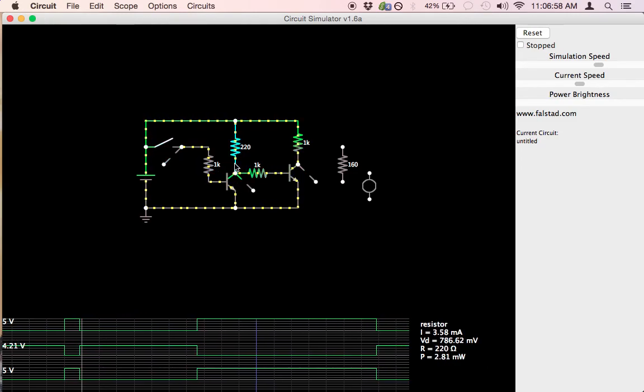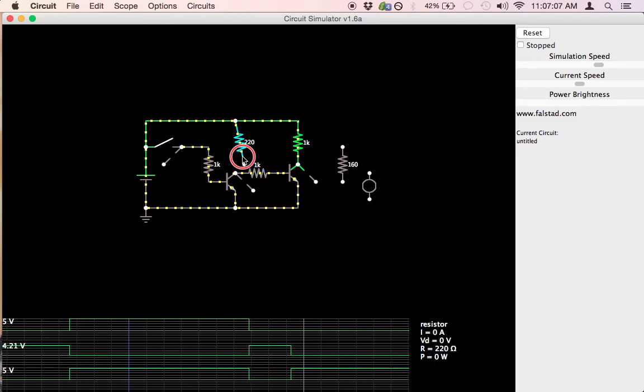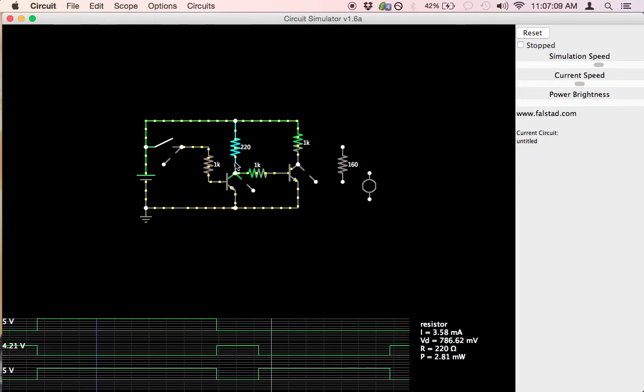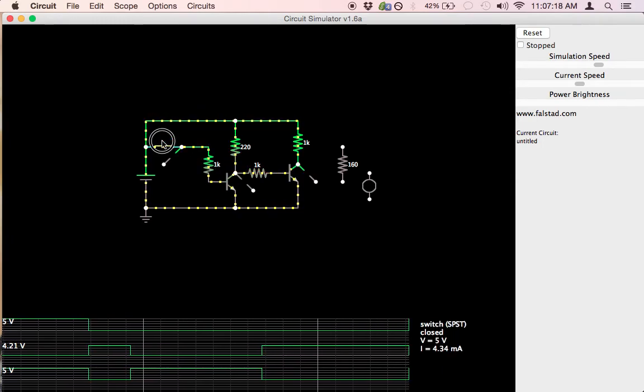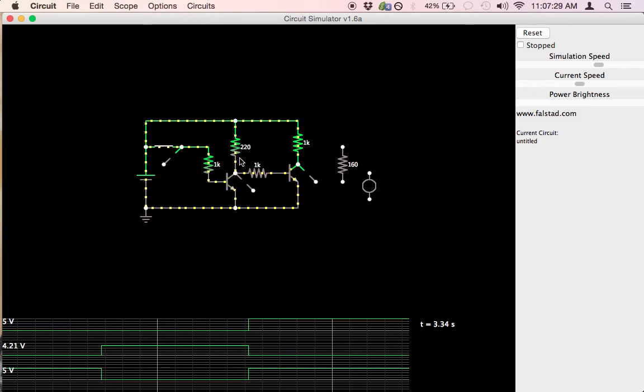By itself, the transistor does nothing. If there's nothing else connected to the collector, there's not going to be any positive voltage there because there's no place for it to come from. That's what these other resistors are for. These are called pull-up resistors, and they pull up the collector to the positive voltage when the transistor is not being turned on. When the transistor is on, it has a very high conductivity from collector to emitter, and essentially the collector voltage is pulled back down to ground. And there's a voltage differential across this resistor.